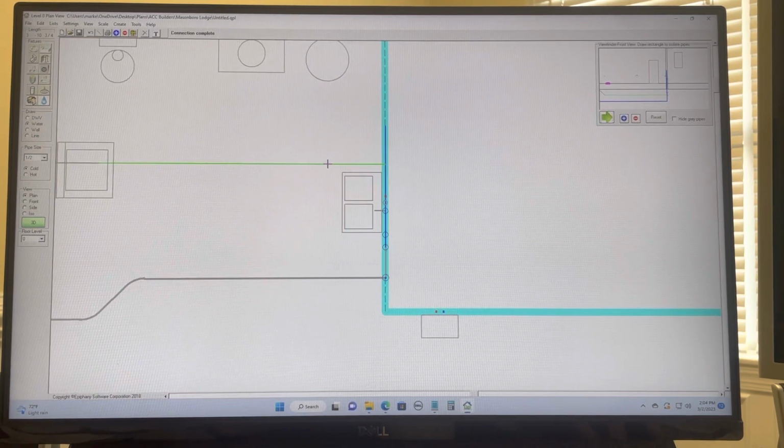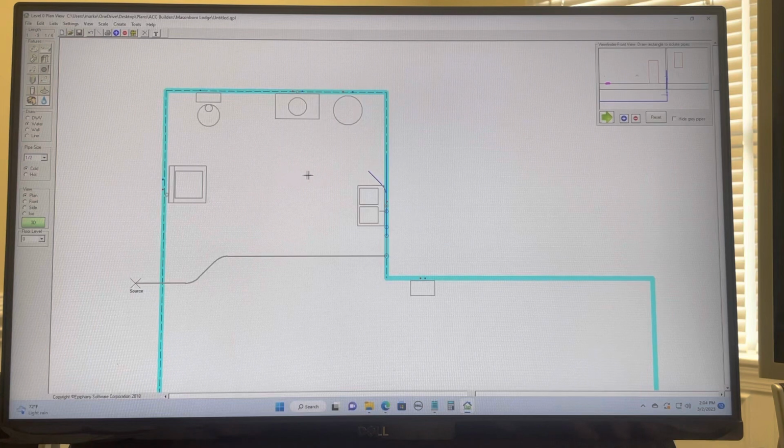We might also prefer to do a 45-degree connection. That way it's not going to generate any fittings in the slab. So now what we can do in that case is just mouse down on the fixture and mouse up on the end of that pipe, and there we have it.